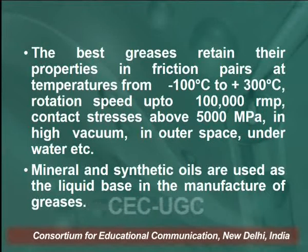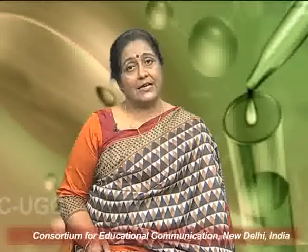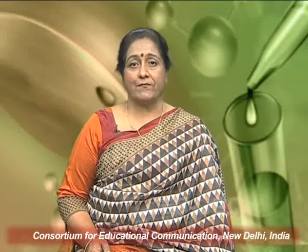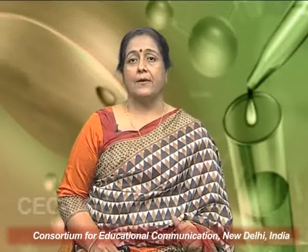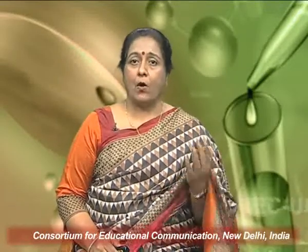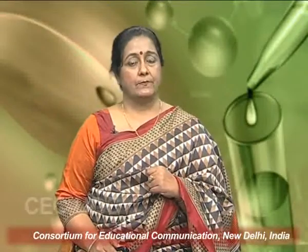Mineral and synthetic oils are used as the liquid base in the manufacture of greases. Greases are generally prepared by saponification of fat such as tallow or fatty acid with alkali such as lime, caustic soda, etc., followed by adding hot lubricating oil with constant agitation.